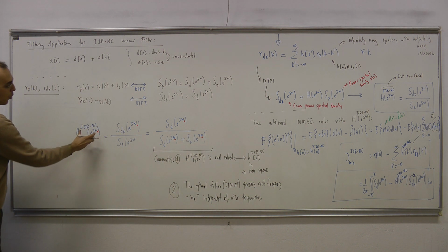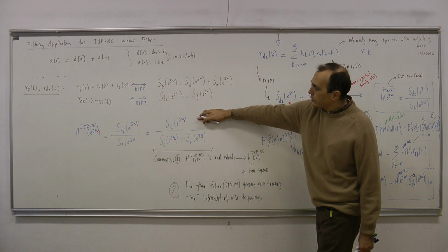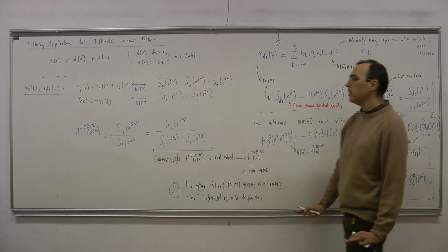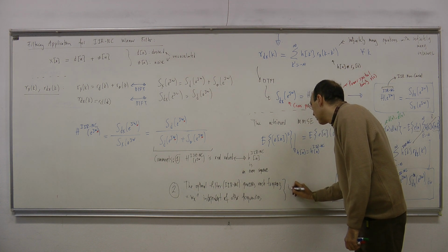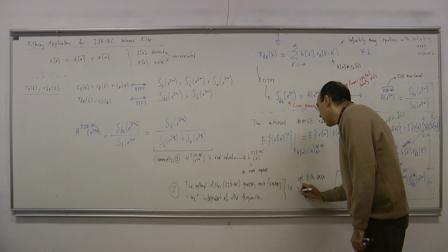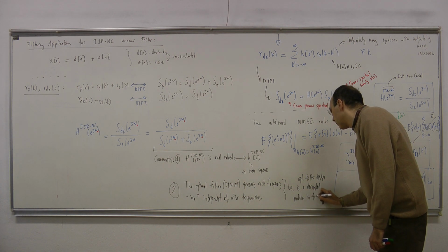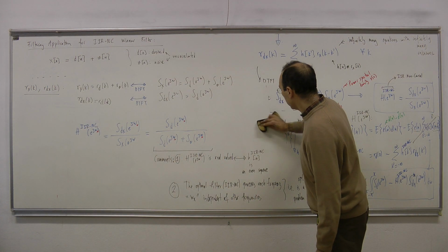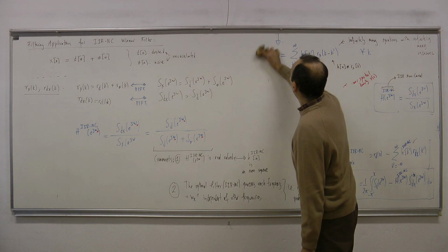So you see that to get the optimal filter's frequency response at pi over 4 or ω_x, you need this information. So you need the information in the desired power spectral density at that frequency and the noise power spectral density again at that frequency and nothing else. So essentially the problem is decoupled, i.e., optimal filter design is a decoupled problem in frequency. So how can I explain these two comments? If our calculations are correct, so we have such results. So can I explain this one?